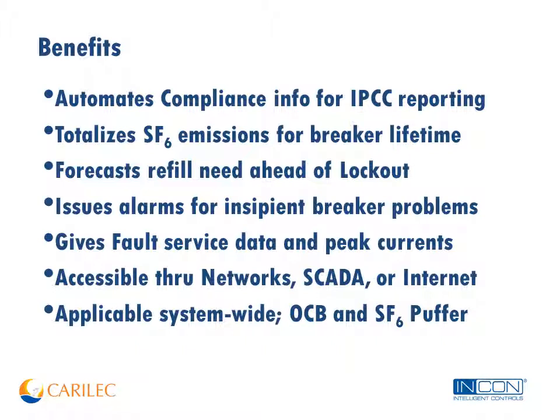You can hook it up to your SCADA system, or you can put the whole thing on the internet. It's applicable system-wide to any circuit breaker, be it a bulk oil circuit breaker, SF6 puffer, air blast, or live tank breaker, even a circuit switcher, which is basically a live tank breaker. So you can use it system-wide.